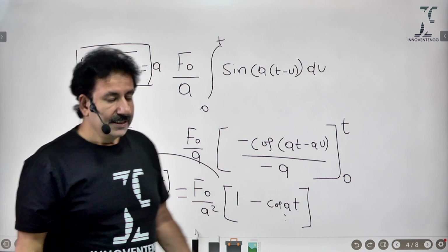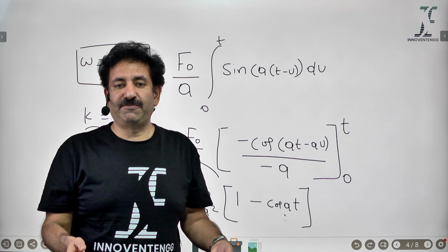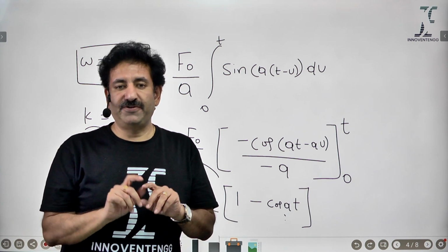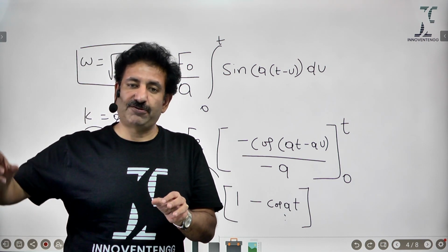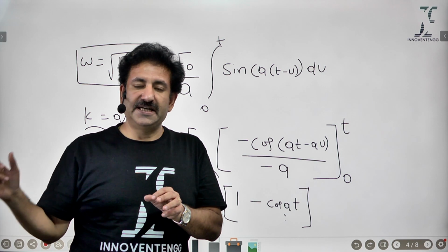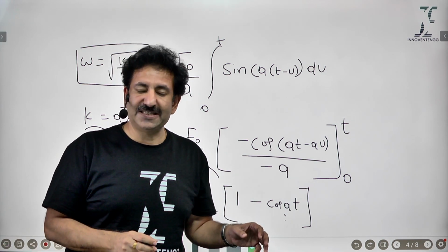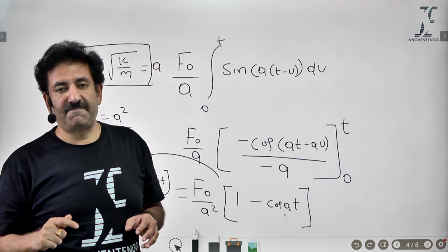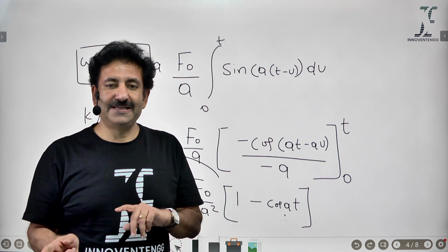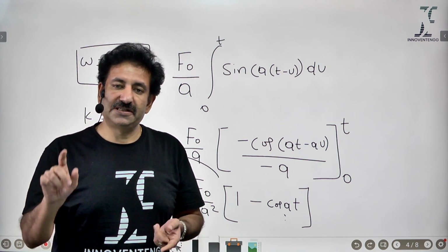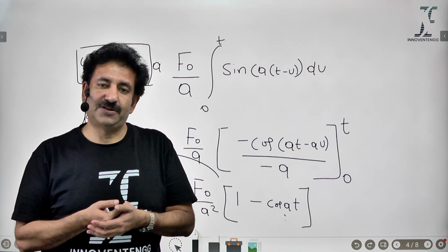So therefore the convolution theorem has a connotation in the realm of engineering applications, and that is what we were trying to unravel. So the most powerful message that you take home is, instead of spending so much time finding the solution of the differential equation of a system and then understanding the time domain response, in a very, very quick and efficient way, you can apply Laplace transform to get to the time response. All that we did was to develop the transfer function and know the input, and then use the convolution theorem to get to the time response.